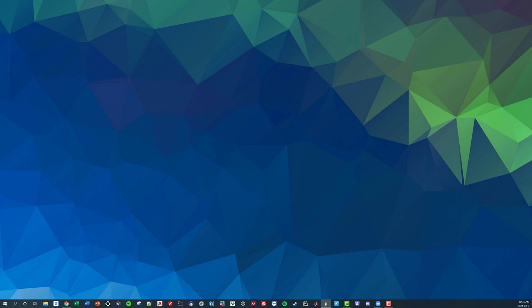But the thing I'm going to show you guys right now is we're going to define what these steps are. As you're going to see, ABAQUS has an automatic step time. You guys can specify the initial step as well as the maximum step you want, but ABAQUS has kind of an automatic solver to try and figure out what these steps are. Another thing that could happen is we do the Newton-Raphson method and it does not converge. Well, instead of trying to go to this point here, ABAQUS will retry, but it's going to pick a lower point. Something like that.